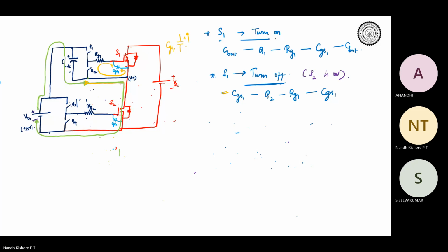So over here, in this particular line, the current is going to be both. It will not affect anything in the switch, top or bottom. It is only because of KCL. If you apply KCL, this particular current will be equal to the discharging current of S1 and then the charging current of C boot. You got it, right?